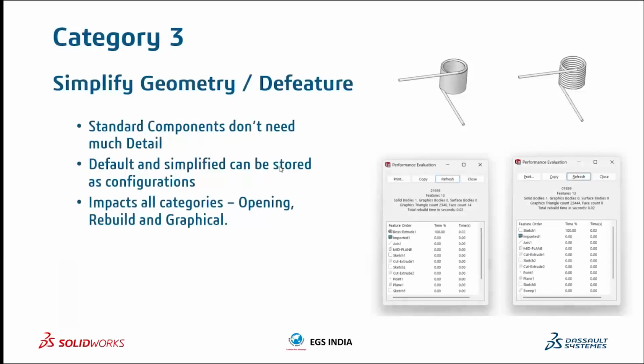And this is another example of the simplification that I told you about. You can see here that I've got a small spring-like feature, where in one version I've covered it with a small extrusion. The other one has the spherical surface on it. You can see that the graphic line count, it's very small, I'm sorry about that, has reduced from 25,000 to 2,300. So almost 1/10 of it. So the resources required for rebuilding or generating this part are also going to be 1/10 of it.